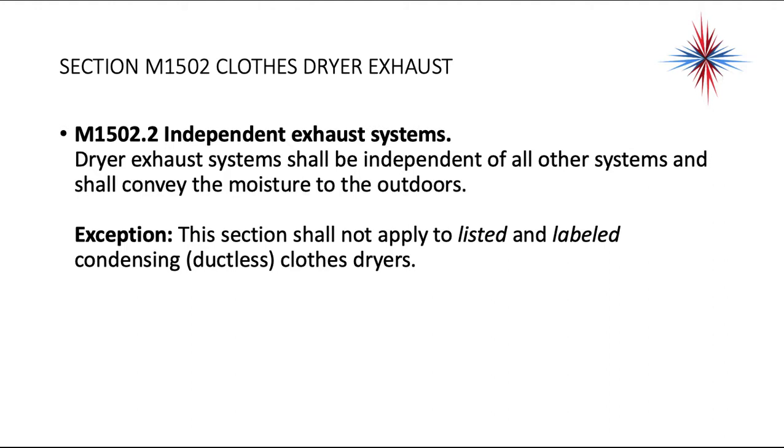There's one exception, and it shall not apply to listed and labeled condensing, which is ductless clothes dryers. And you don't see them that often. But if there's a dryer exhaust, it has to be independent of all other exhausts.